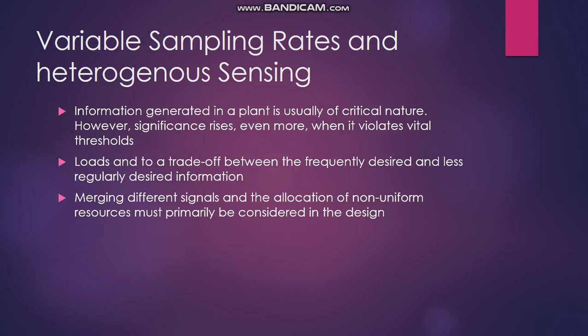Sensing is used in the sense of quantization information and the number of bits assigned to the sensed data. In IWSN, it is of paramount importance that the data from the different sources be treated according to the nature of knowledge, not only in the sensing priority but also regarding the sampling rates and affordable quantization error of the sensed information. Therefore, heterogeneous sensing, though rarely used, can make a significant difference in reducing the load on the stressed network.